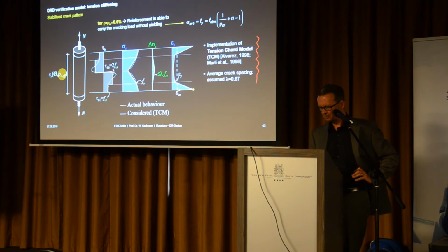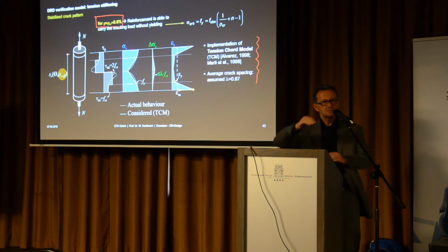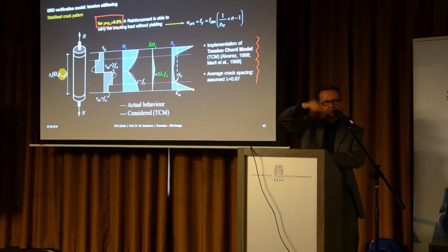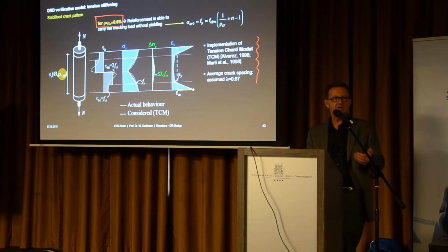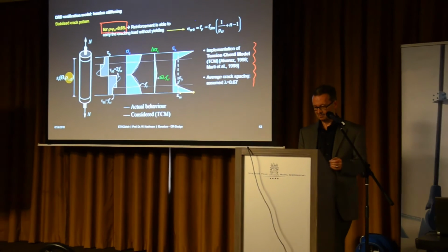Now this works for minimum reinforcement, at least, or more. So the rebar does not fail when the crack appears. If I'm below that with the reinforcement, and I'm quite often, because the stirrups have minimum 0.2% of reinforcement. If you would do a tensile test in the direction of a stirrup, it would always rupture, because it's much below minimum reinforcement. But we know it doesn't, because the cracks are controlled by other parts of the structure, the chords in a web, for example.